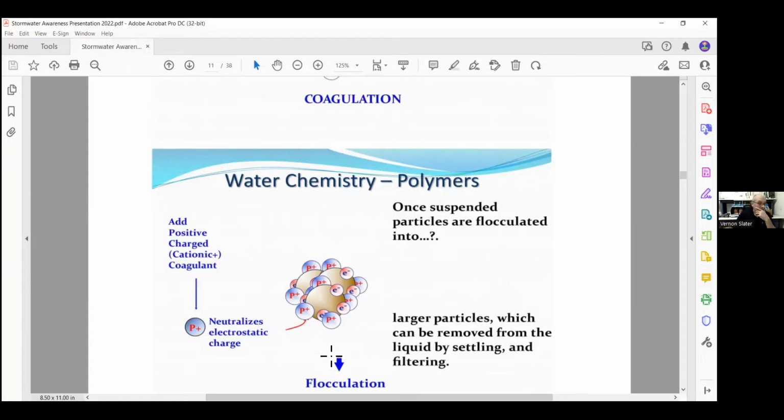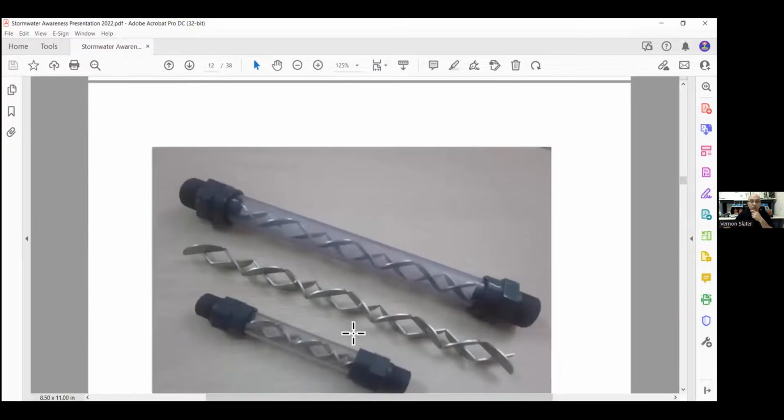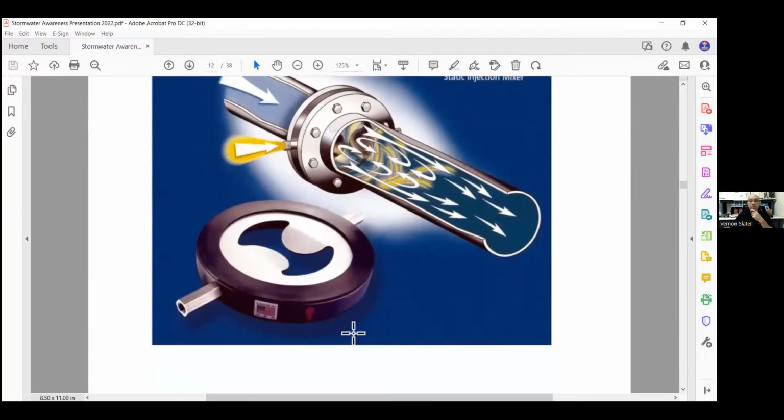In more detail, the dirty water is collected where some of the heavy solids settle out in sand and gravel. This water is then bench tested to find the best starting dose. With the dose known, the raw water is pre-treated using a static mixer for a flash mix. This step is followed by about 30 seconds of secondary mixing as the water flows through the plumbing and into the tank or basin. Now that pre-treated water flows through a tank or basin for about 90 minutes. So here are our static mixers, a couple of different types.